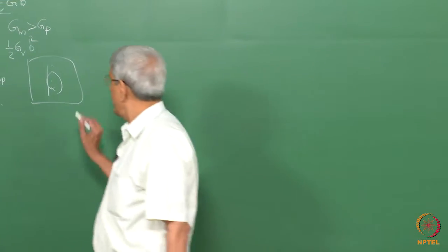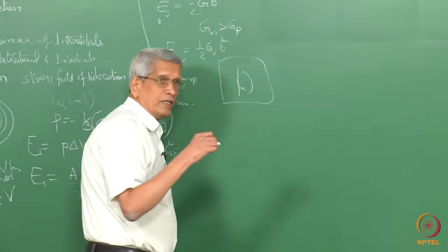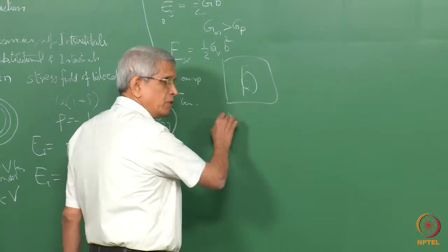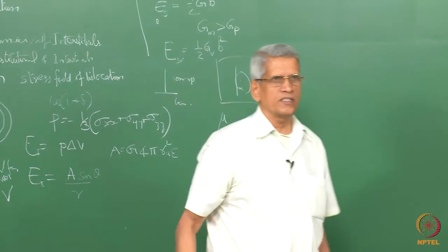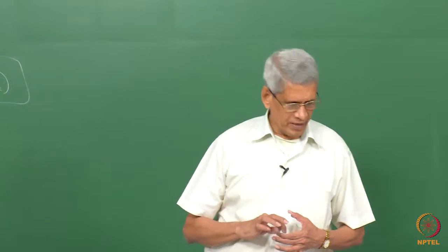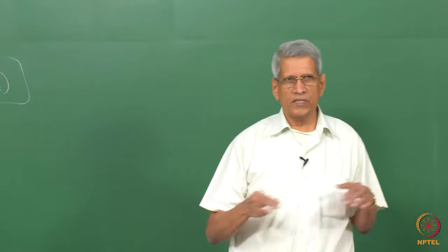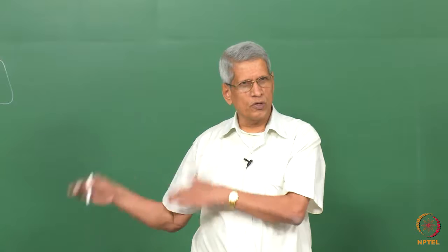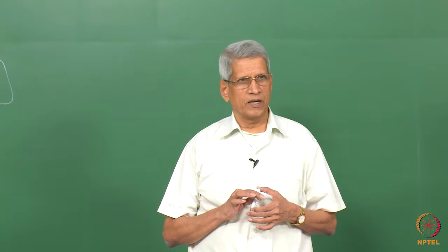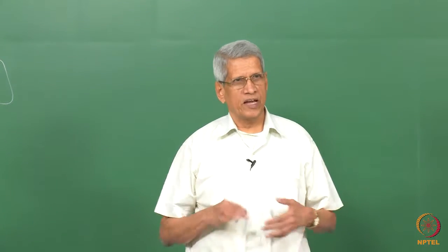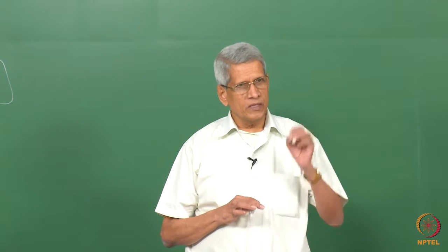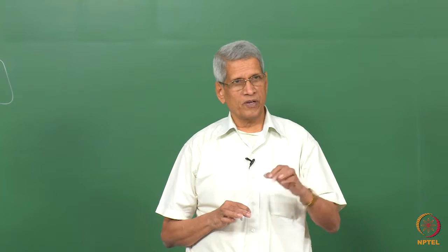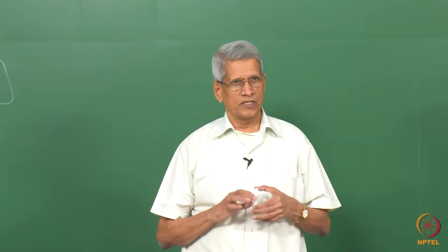Not only that, since the chemical composition also can be different, the chemical potential between the faulted region and the unfaulted region will also be different, right? What will be the effect of this change in chemical potential? More solutes can come into the stacking faults and segregate to them. So that's another way in which they are attracted to it. This effect is called the Suzuki effect. This is another type of effect with which solute segregation will occur.